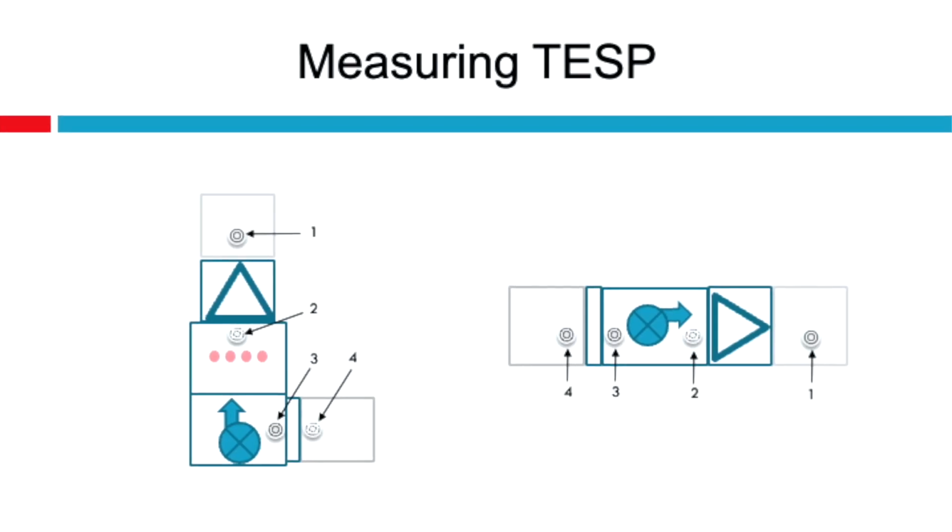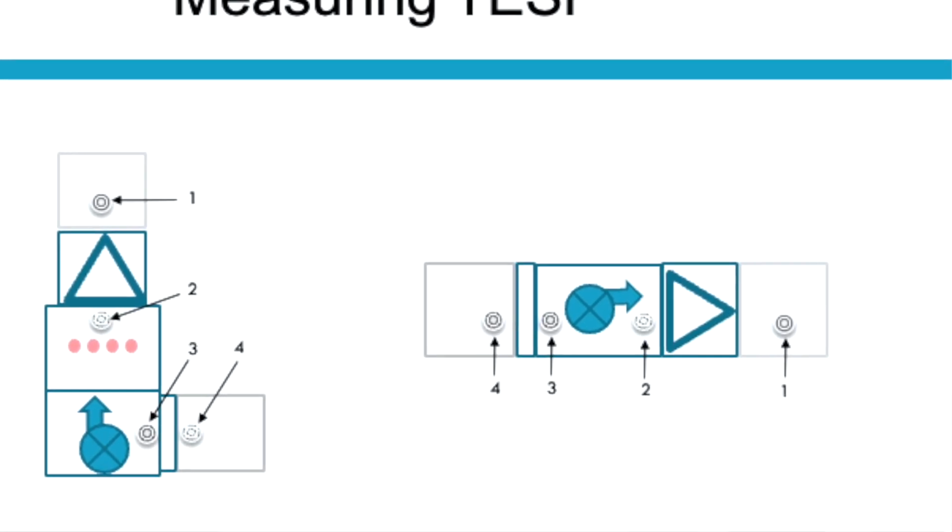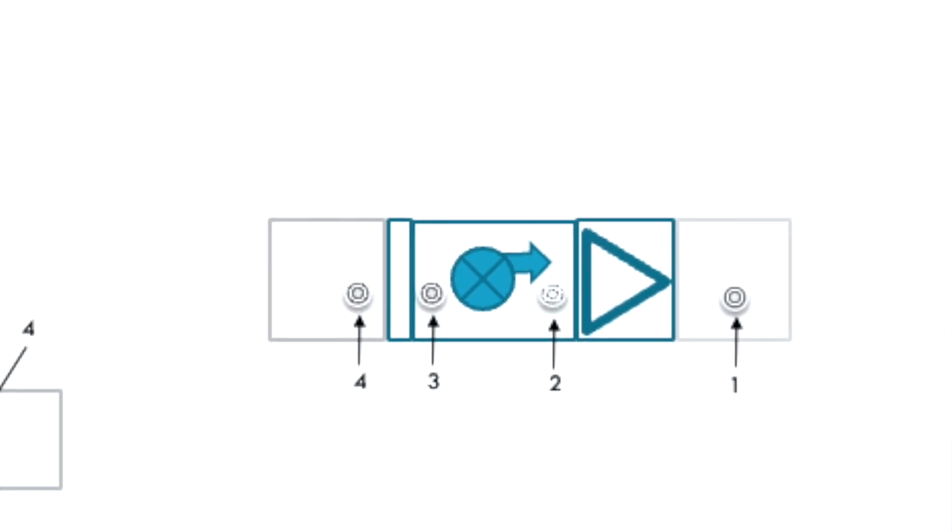Now, when we're working on an air handler, let's say for a heat pump or an air conditioner, it's really simple because the blower is shipped in the same box that comes with the A-coil. So since it's all in one box, if you don't change the filter that ships with the system, which let's be honest, most people do, but it's probably like a MERV 1 or 2 rock catcher, we'll call it, you can stick that static pressure probe into the return duct and then onto the supply duct right after that blower, and you're going to be able to add the two numbers together to get your total external static pressure. Now remember, in the return side, it's going to be a negative number.